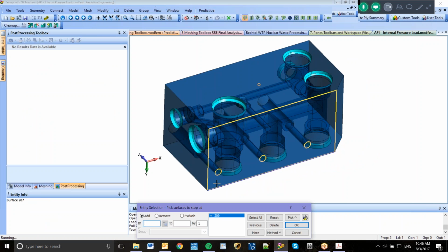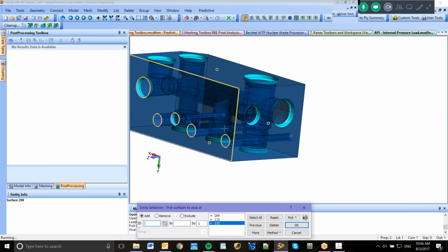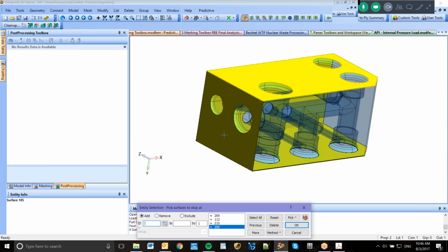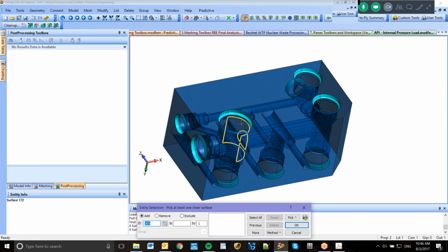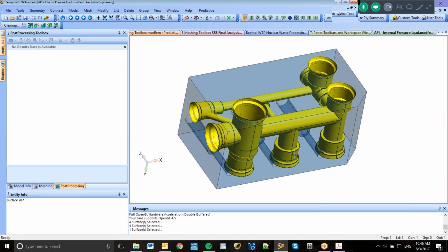So it says, select the surfaces where it terminates. And I'll hit the button there. That looks right. There's nothing on that end. And then it wants a surface from the inside. Watch what this does. It makes a group of all the surfaces you need for your pressure loads without having to pick all the way around. And so this is written up by part of the Femap development group, and now we have it in our toolbox.